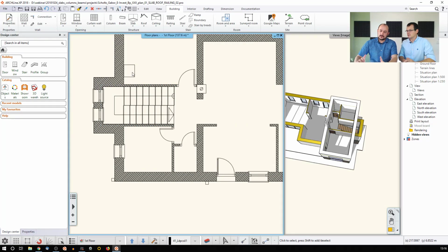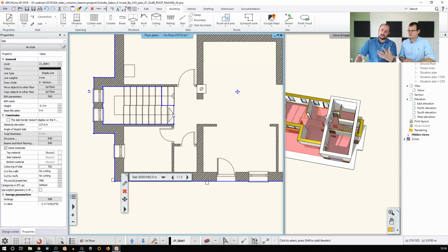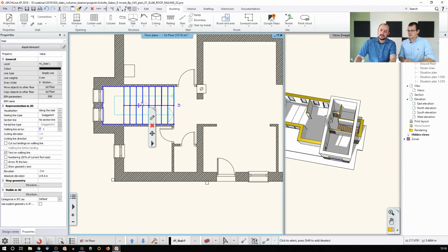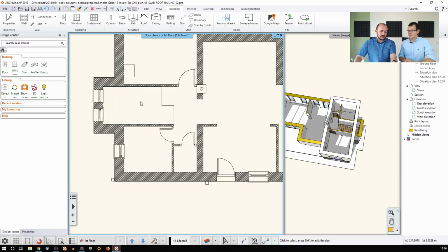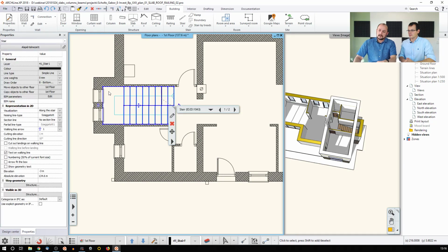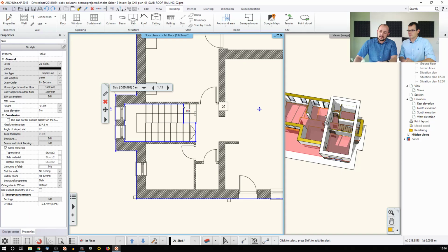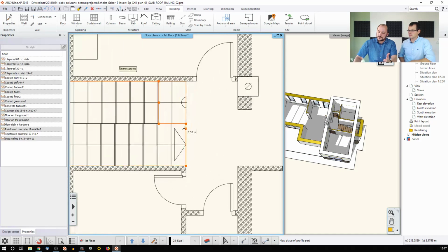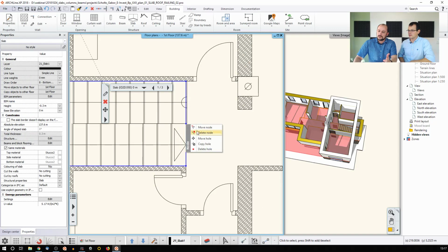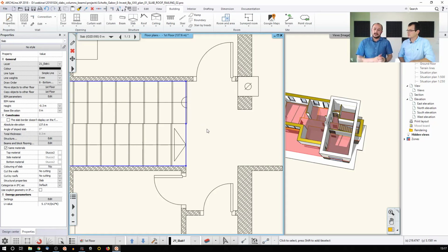Yes, of course. Now I just jumped to the first floor because that's where the contour lives, and there I can see the cutout contour. If I hide this slab, I actually erased it, so I just undo that. I can see the contour. See, this is the contour. So if I click there, this is the slab contour. This works just the same as a regular slab contour. You can just click here and use an offset, make it rectangular, even remove the node from here or move it to another place. So it works and lives the same way.